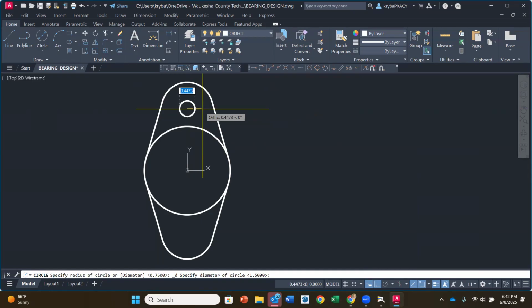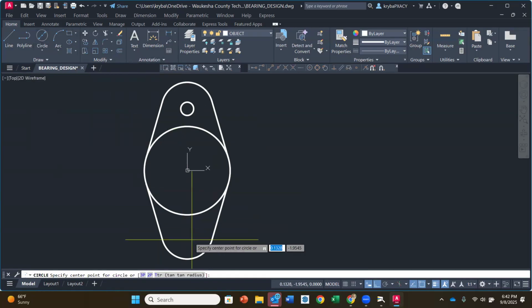And then for the diameter, I'm going to put in 0.375 first. I can do that very same thing. I can hit enter, go back down, activate that center here, and type 0.375 to, oopsie, that was a radius. Sorry, undo. See, you can just do U, center, diameter. There we go, 0.375.